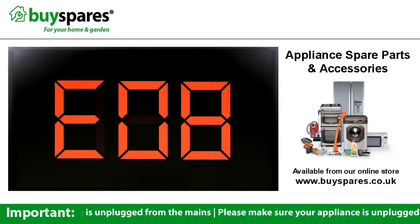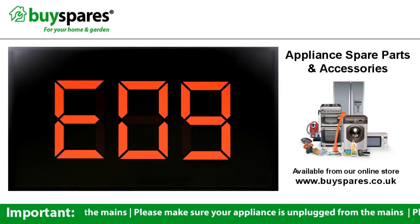E08 error indicates a problem with the motor tacho. This will usually result in the motor spinning to high speed and then stopping. E09 is a motor triac fault error and you may not have any main motor drive.